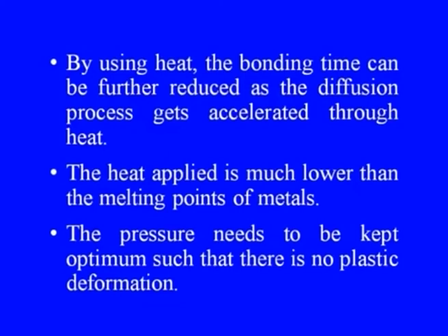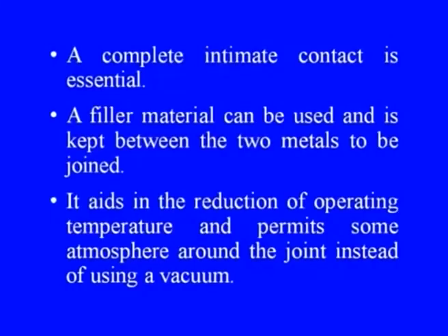The pressure needs to be kept optimum such that there is no plastic deformation. A complete intimate contact is essential in this process. A filler material can be used and is kept between the two metals to be joined. It aids in the reduction of operating temperature and permits some atmosphere around the joint instead of using a vacuum.